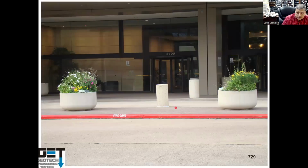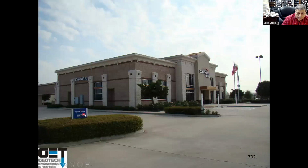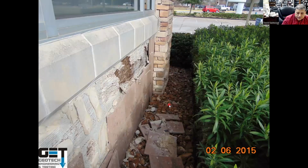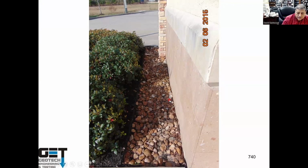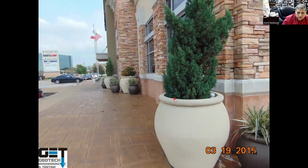Put pots around the building. No plant areas. This is the Capital One building on Westheimer. It had a lot of movement. They were watering all these planters. You go out there, you look at it. The sides were cracking up. They had bed liners here. It was holding the water next to the foundation. All the tiles were coming out. There was sheetrock cracking inside. Bed liners. We put pots there. Closed up all the bed liners and put pots in it. Stabilize the area.